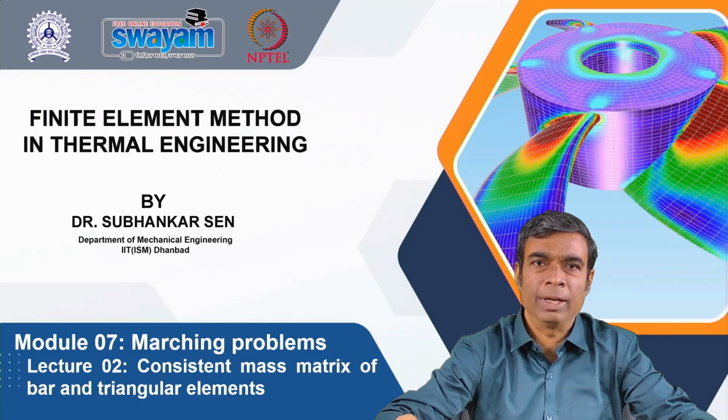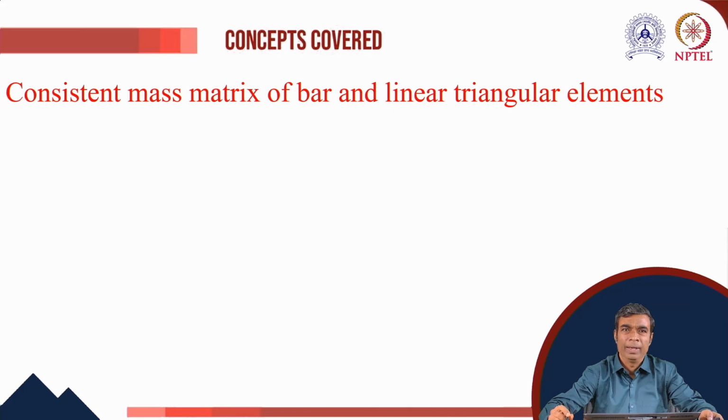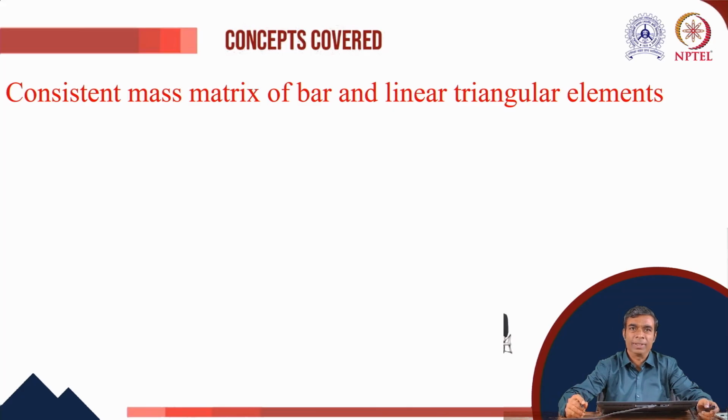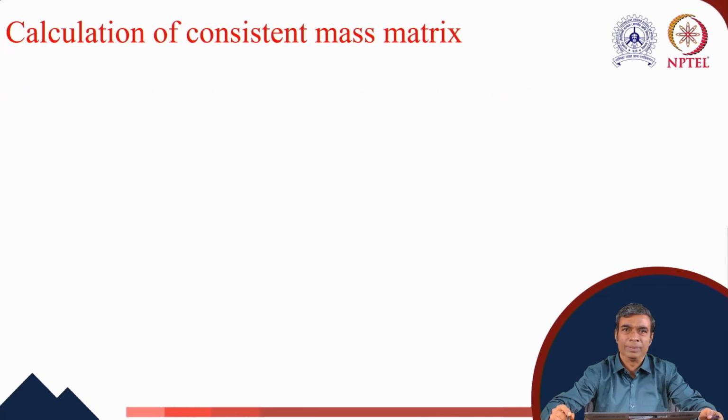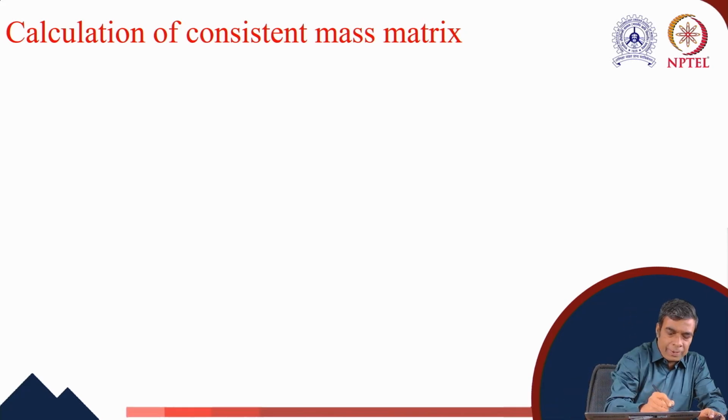of Module 7 of the 12-week SWAYAM NPTEL course, Finite Element Method in Thermal Engineering. In today's class, we shall illustrate the computation of consistent mass matrices for the two-noded and three-noded bar elements along with the linear triangular elements. So we shall show the computations by using exact integration, and in a few cases we shall also show them by using the Gauss quadrature.